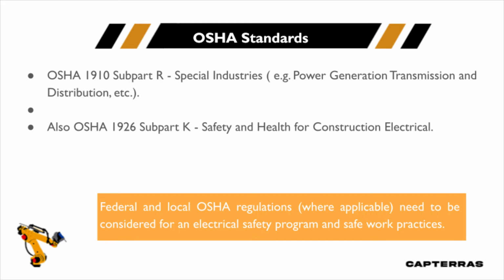Even though you may say, well, I'm not a utility generation facility, that's okay. OSHA recognizes industrial sites and sites that have on-site cogen and other medium voltage distribution, things that look more like a utility system, as requiring specific work practices and regulations. So you will find those in OSHA subpart R. They will also cover the specific requirements for picking PPE in outdoor substations and overhead lines, and the types of calculations that are allowed for determining your PPE in those environments.